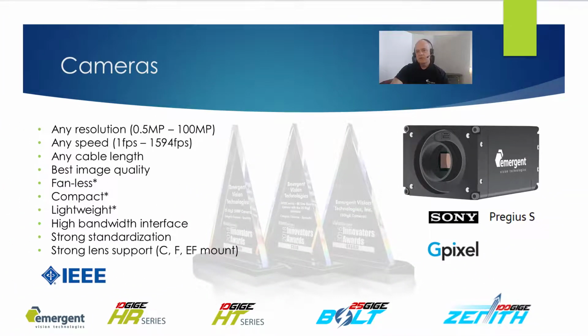So how does one go about selecting a camera for the volumetric capture camera array? Resolution for typical systems is in the area of 12 megapixel to 25 megapixel, but we've seen also as high as 65 megapixel or even 100 megapixel. This decision is based upon the spatial accuracy required and thus number of invisible markers as mentioned previously.